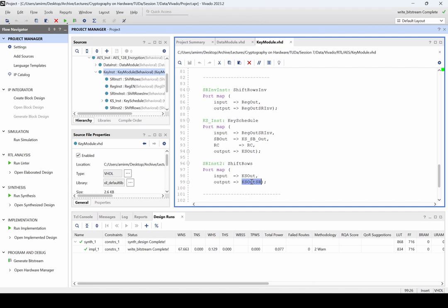This is always like this, that there is a trade-off, and you have to find a way which suits your application best. Sometimes reducing the area consumption is important, but not at the price of having a very high latency or very low throughput. But sometimes it doesn't matter how long it takes, and it should be the smallest implementation of the AES you can provide, because in some cases the speed of implementation, the latency or throughput doesn't matter at all.